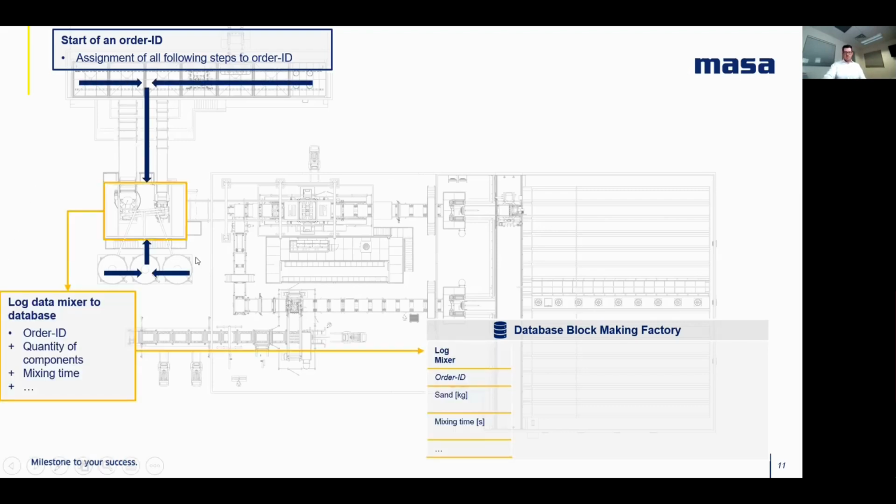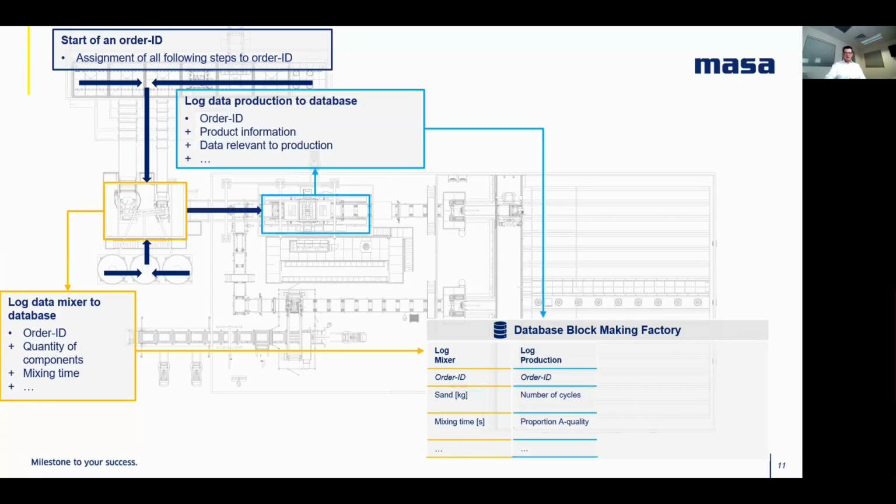So onto the mixing and batching. Here we have our order ID, and that's going to trigger our raw material requirements. How much cement, how much aggregates, how much water, how long are we going to mix this product for? Is it a through mix product? Is it a face mix product? Once that process is complete, it gets a timestamp and goes onto the machine.